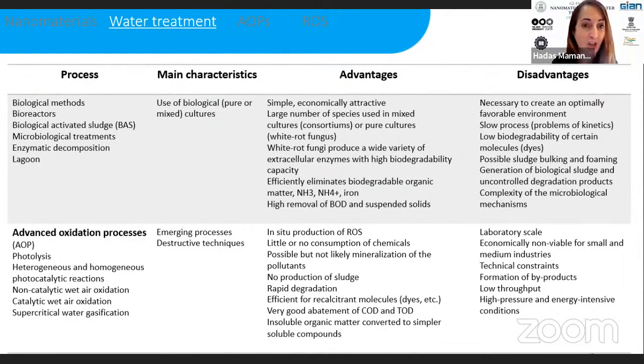But if we combine AOP with a biofilter, for example, and this is a pilot that we had in one of the wastewaters, where we combined ozonation-based AOP with a high rate biofilter, then the AOP oxidized the micropollutants, and then the biofilter finished the process. So with the post-AOP biofilter, we didn't have any residual pollutants left.